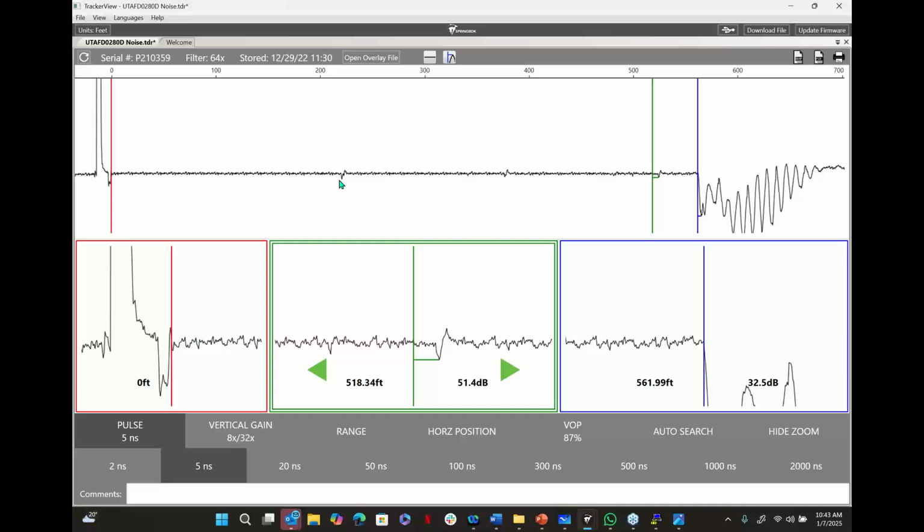As it turns out, both of these happen to be wet splices, corroded splices, and that was the problem. All he had to do was just hit store, send it to me, and we were able to determine that as if I were connected live. Totally kick-ass, you feel me?